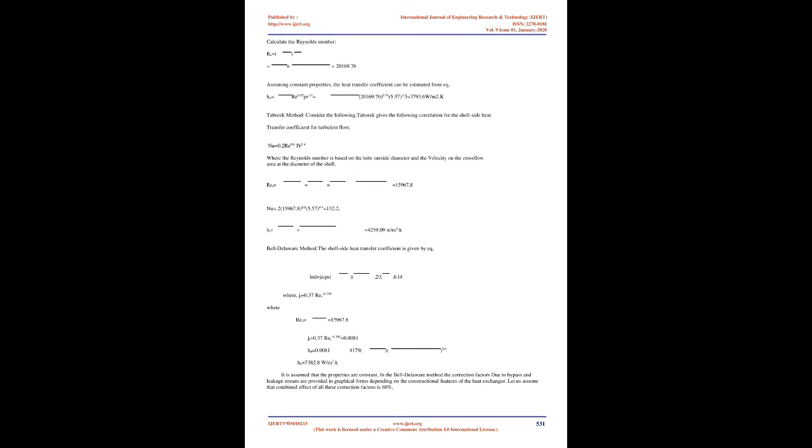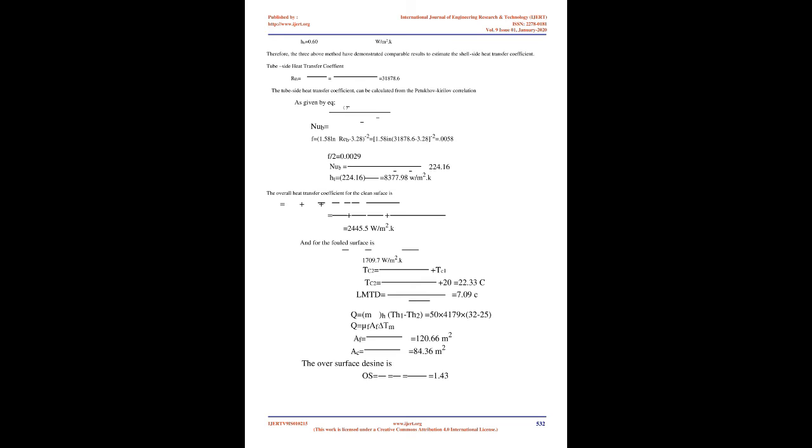A first design is chosen, complete in all details necessary to carry out the design calculations. The design chosen is now evaluated or rated, as to its ability to meet the process specifications with respect to both heat duty and pressure drop. Based on this result, a new configuration is chosen if necessary, and the above step is repeated.